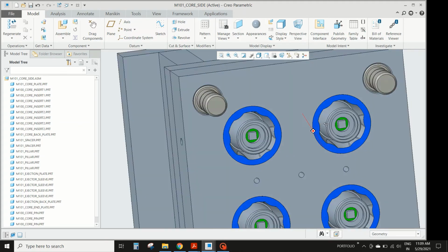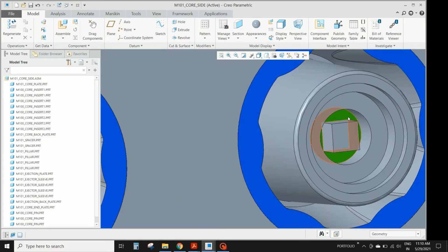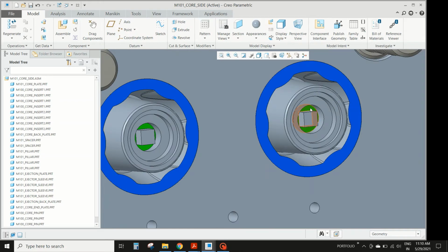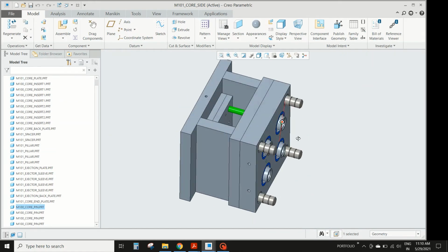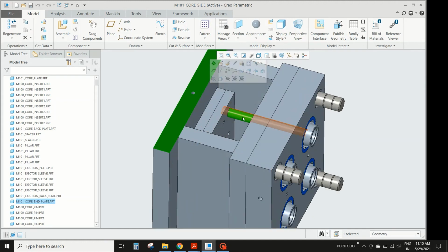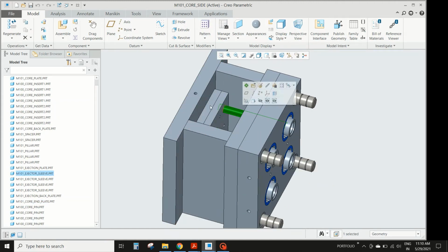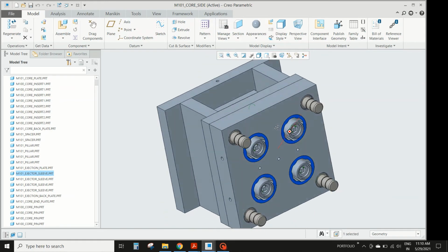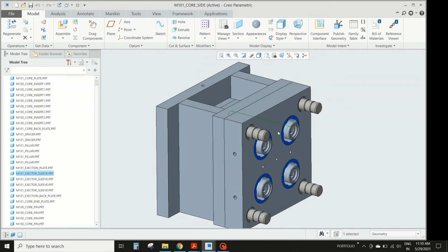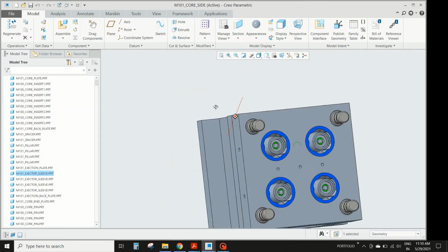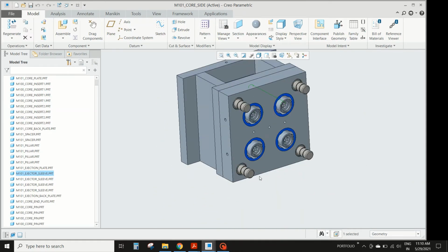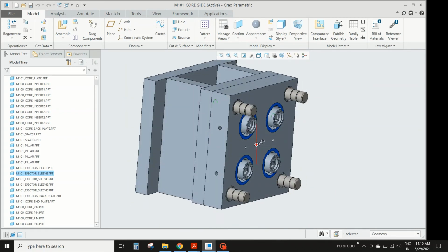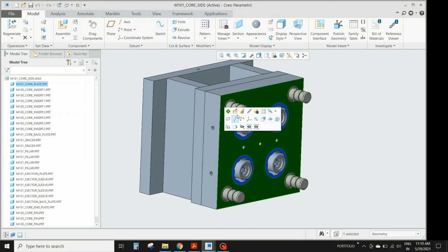This mold part is ejected using a sleeve ejector. So you can see, this is the sleeve, and this is the core part which is attached to the back plate, and you have a sleeve over here which is used to eject the molded piece. This layout of the mold is basically 300 by 300 mm, and I made it a very simple design so that the manufacturing is easy.